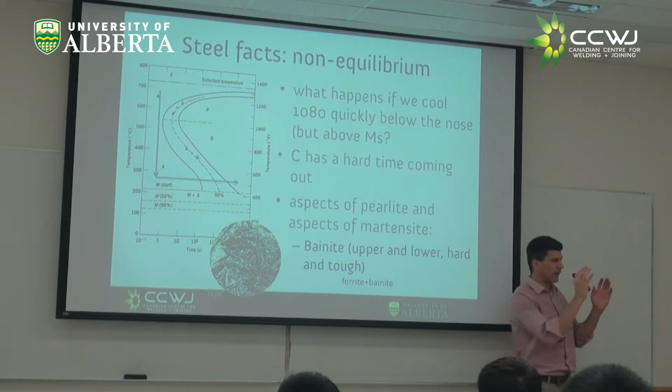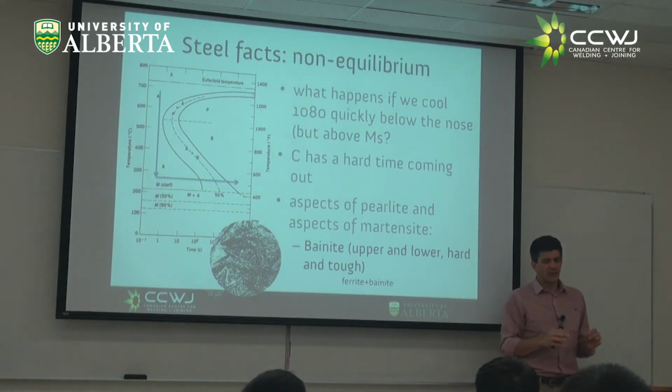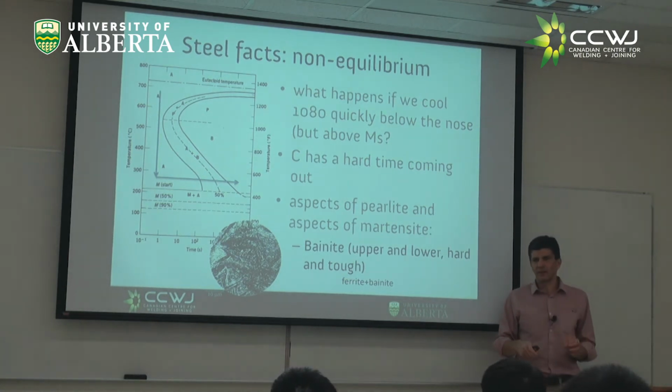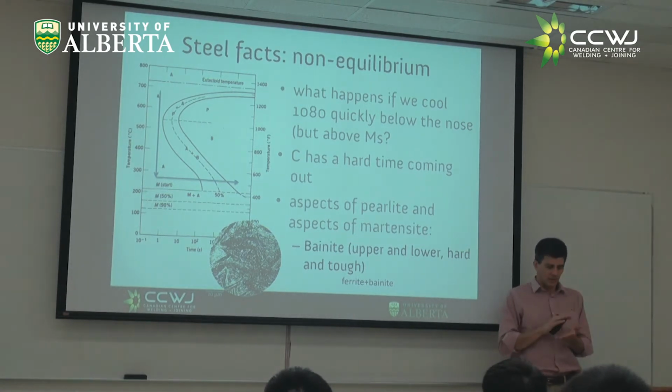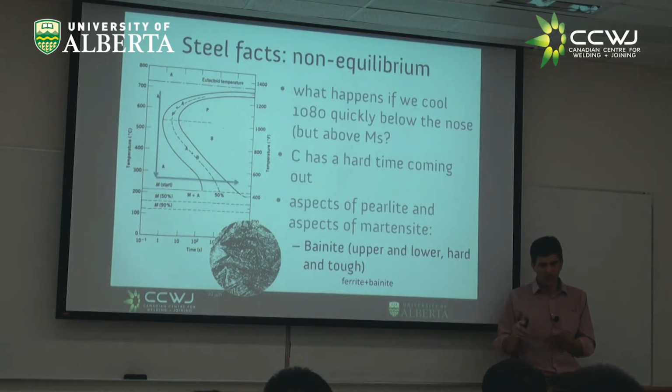So when a metallurgist talks about bainite, they tend to talk upper bainite, lower bainite in a somewhat abstract sense. In welding, these bainitic transformations, this hybrid of displacive, like martensite-like shear and diffusion, they have many different aspects.